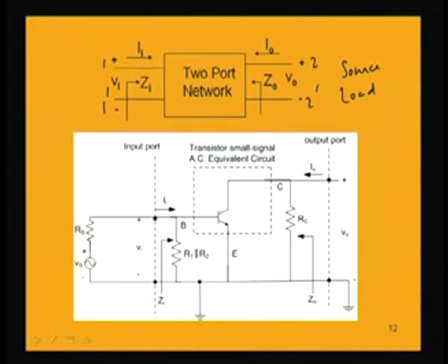So, in this two port system there are quantities: input voltage, input current, output voltage, output current, and conventionally the polarities and directions are shown like this. That is, the upper point is positive with respect to the lower point for these voltages, and the currents are towards the system. I1 and I2 are conventionally shown towards the two port system. So, V1 I1, that is Vi Ii, are the voltage and current at the input port, and V0 I0 are the voltage and current at the output port.